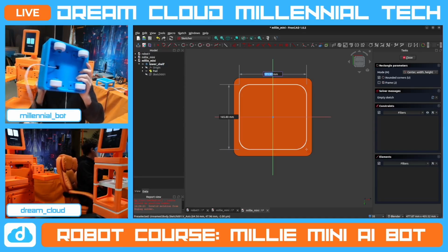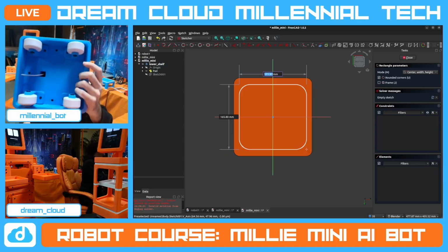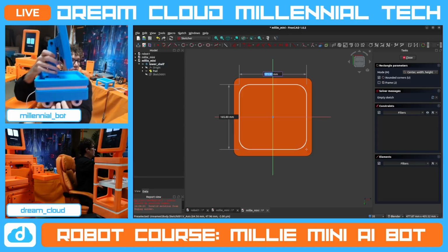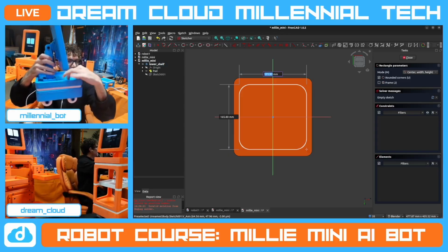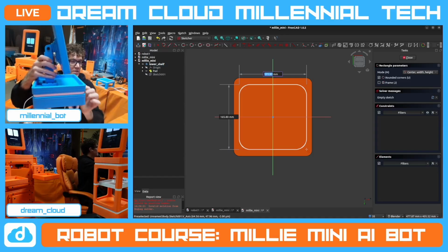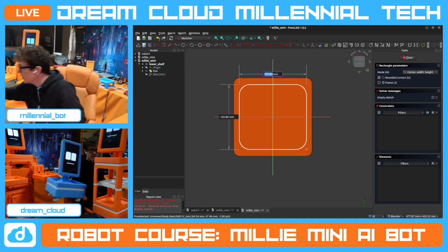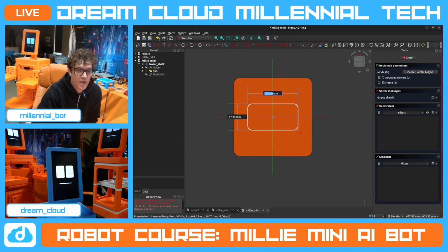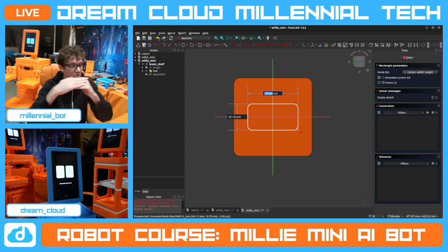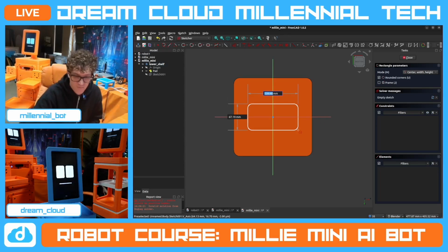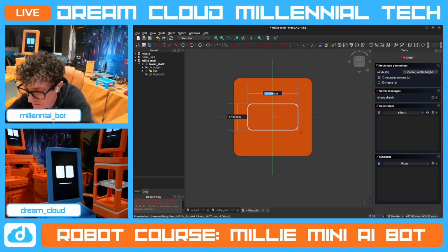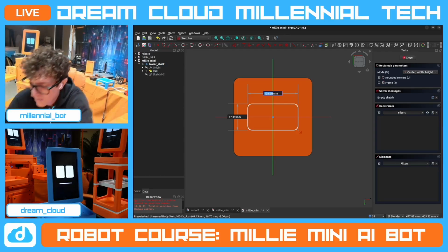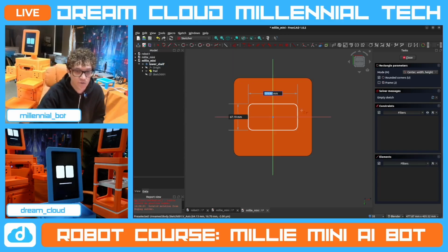So even if we have screws that are just going through the bottom and they're being bolted into this top plastic, there's a middle section here that essentially allows us to hide that seam. So you don't see where the two pieces come together. And that's just something that you have to think about when you're creating parts in general.